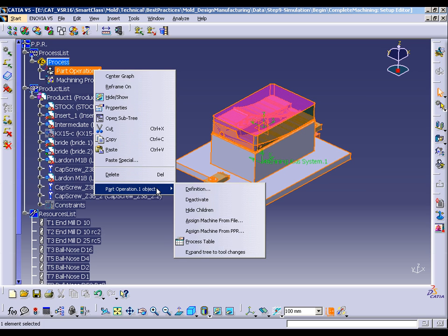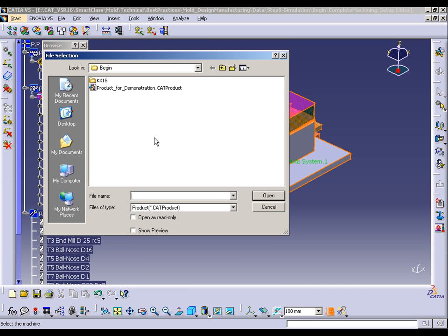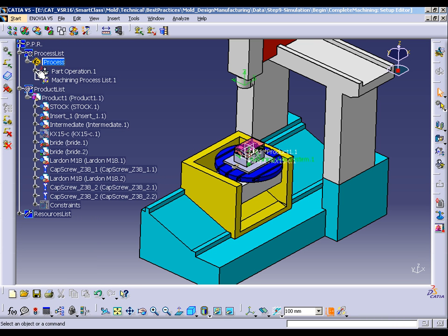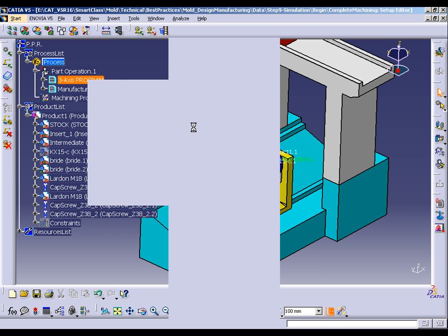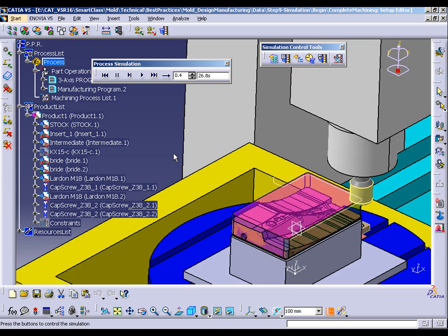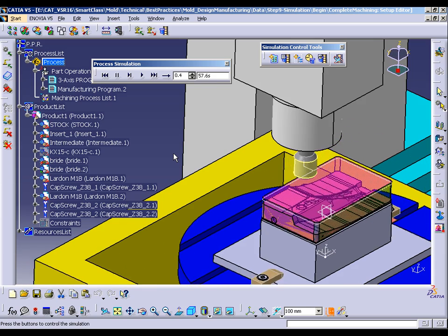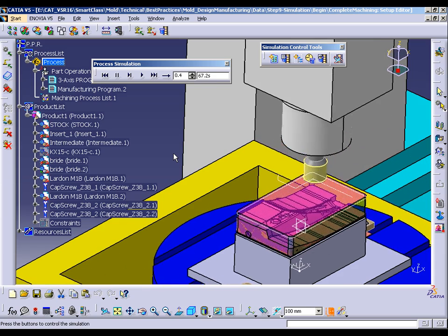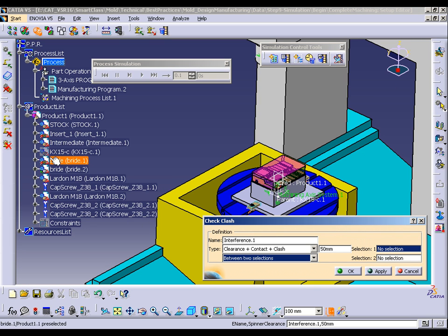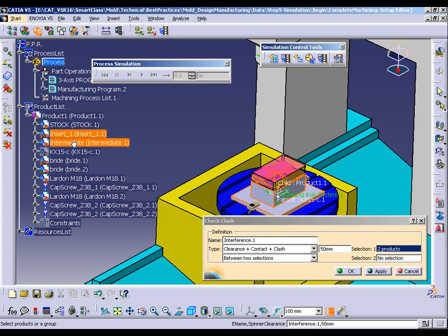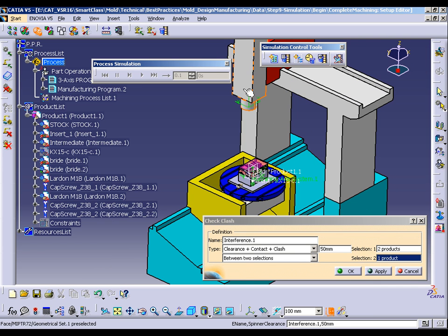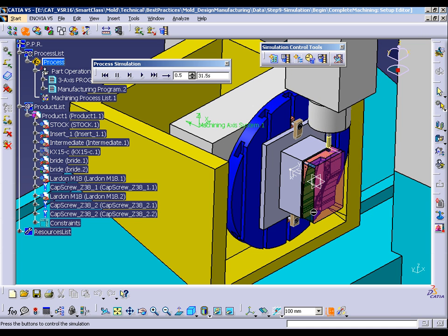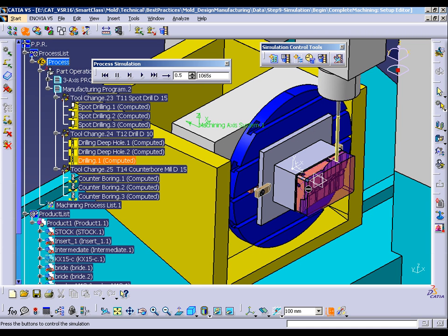A key feature of CATIA V5 is the capability to perform integrated machine simulation thanks to the single infrastructure holding the part geometry, the definition of the NC tool paths, and the synchronized ISO code driving the machine. This allows an early detection of errors, like collision between the workpiece and the tool. This unique approach avoids lengthy back and forth exchanges between different softwares, like what other CAM systems have to do.